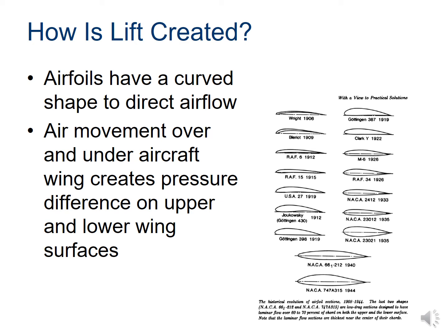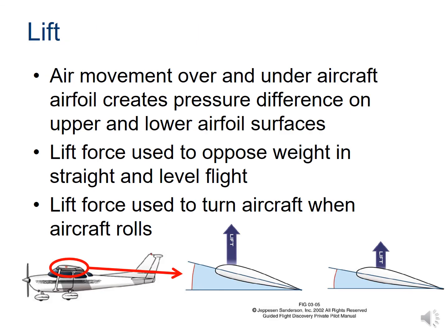A thinner airfoil will make for a faster plane, whereas a thicker airfoil will require a lot of thrust and be slower. Air moving around the airfoil causes a pressure differential which produces lift. Besides the wings, other examples of airfoils on an aircraft include the propeller and horizontal stabilizer. The concept of lift is applied to other devices such as wind turbines and automobile exteriors. Lift can be increased without changing the wing or airfoil shape by decreasing the angle and increasing the speed.